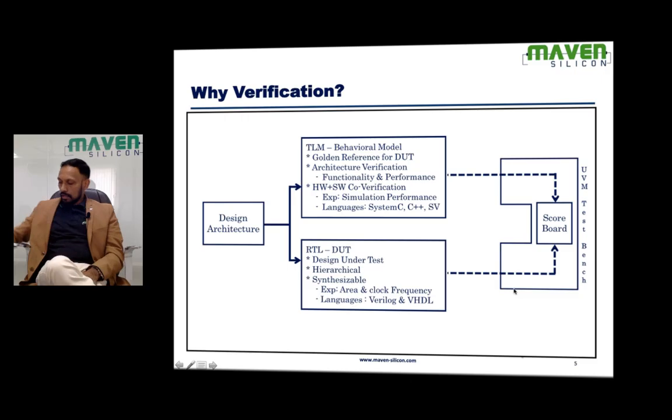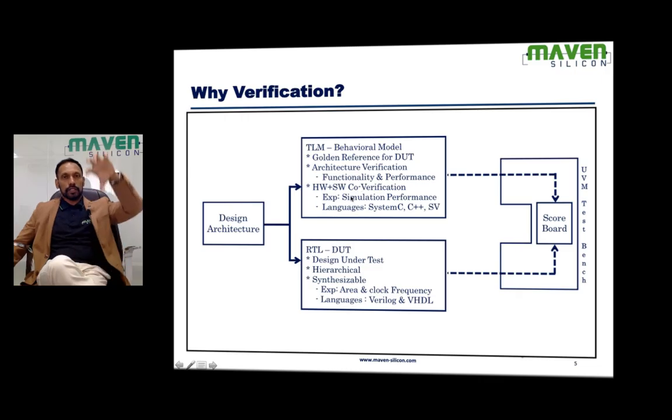During simulation, we use this TLM to produce the expected values. So we are going to instantiate this TLM as part of our SystemVerilog test bench. This is going to be the golden reference for the DUT. And when we generate stimulus, look at this input side.